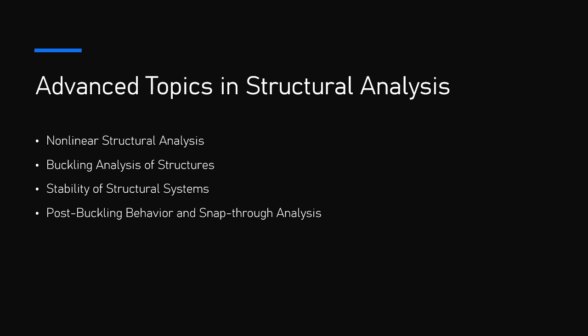In these cases, the structure may not fail immediately after buckling, and it may still be able to carry loads through large nonlinear deformations. 10.1. Post-buckling behavior. Post-buckling behavior refers to the way a structure behaves after it has undergone buckling. After a structural element experiences a critical buckling load, the point at which it starts to lose stability, it may continue to deform, but it can still carry some load.